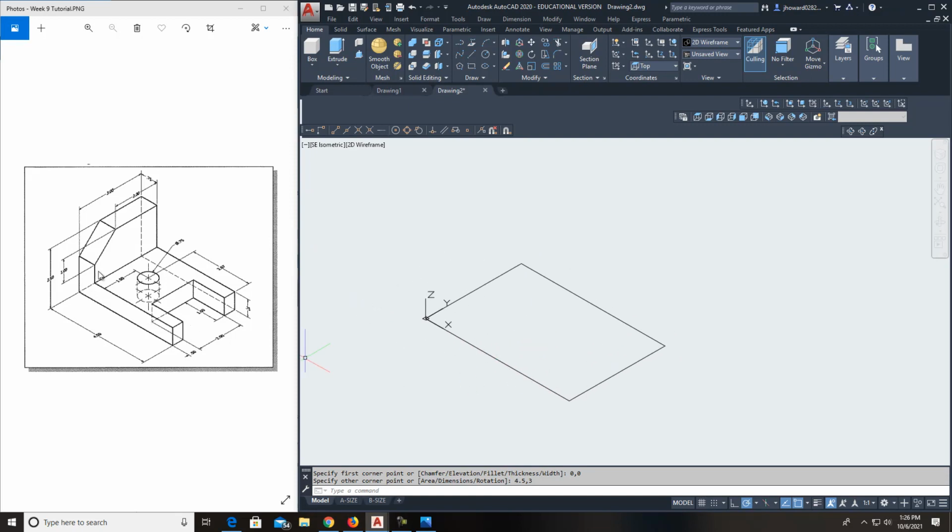As you can see, that's for the base, and I'll come in here and get the rest of this finished in just a little bit. We can go ahead and do it now. Remember, you're only drawing in your XY plane, and this will make more sense as we go on. But I want to click this one and explode it. So modify, here's my explode, so they're individual pieces, and I'll do an offset of 1/2 inch.